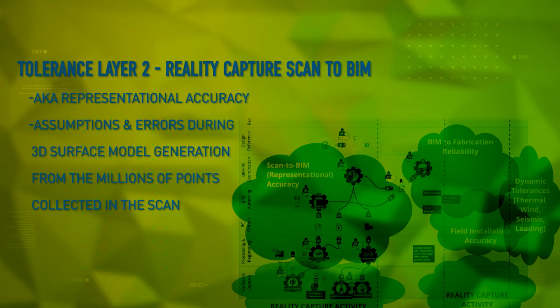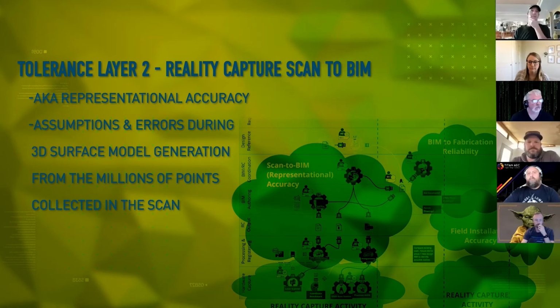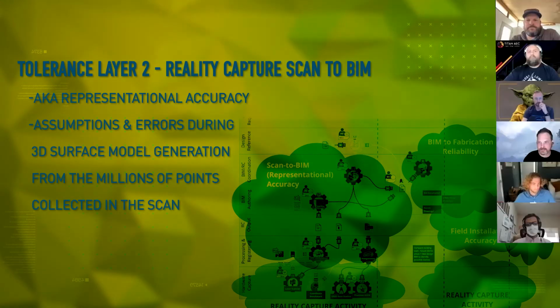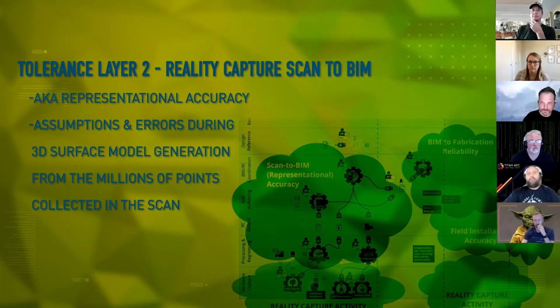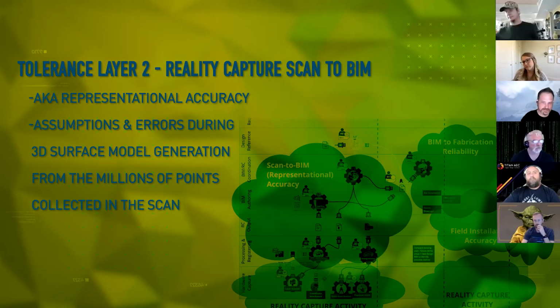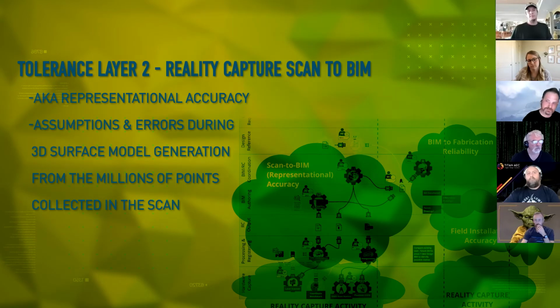Oh, go ahead. Yeah, the one way that we kind of learned this was understanding the back end, the registration process itself. And so that's where we learned to do more scans. We would crank down the accuracy. We had a TX6 at Excel, and we were using the 2.5 minute scans, but we were doing more scans. And then when we took it into RealWorks to start the registration, we'd sample those scans down into like a 20 meter radius. And that really helps that registration, right?